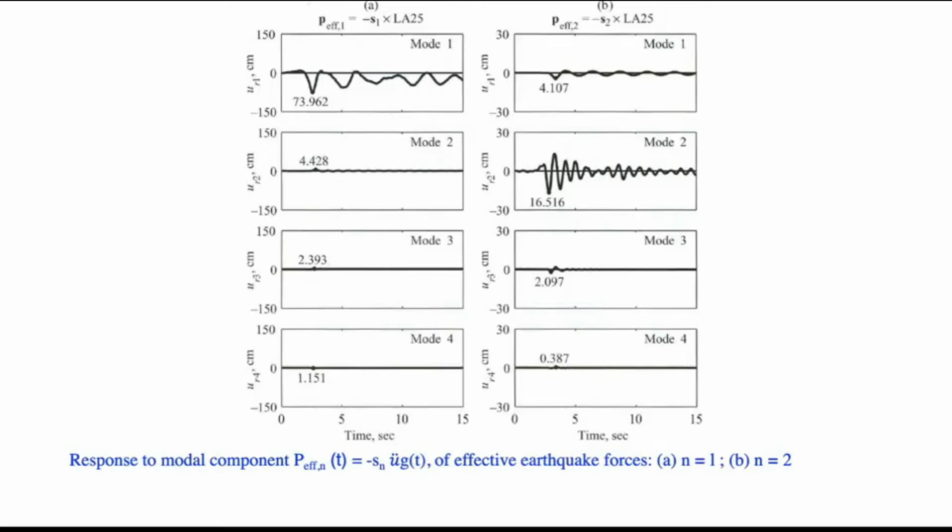When these forces are applied, you can see the responses, but the other modes, mode 2, mode 3, and mode 4, are also contributing something. It's a very small contribution, but it is also contributing some deformation. It's not zero. It basically happens that when yielding occurs in mode 1, the higher modes are also excited. Initially, when there is only elastic behavior of mode 1, the other modes are not contributing. But when yielding happens in the structure, then the other modes start contributing in the deformation.